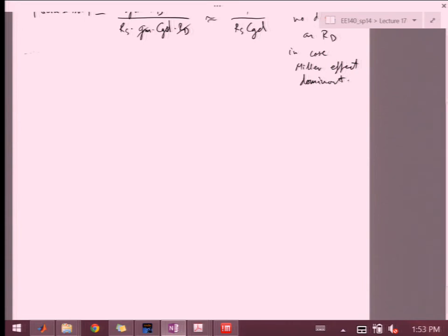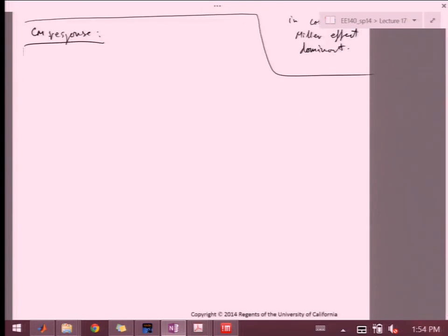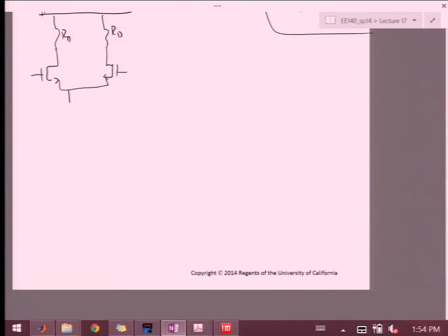So this was the differential response. Let's take a look at the common mode. For the common mode, we will use a different half circuit. Let me first draw this one for completeness. Now, here, I have to include a few other things that I didn't draw in the previous case, because in the previous case it didn't matter what's really in the tail, since in differential mode the tail will be grounded. Here, it sort of matters.